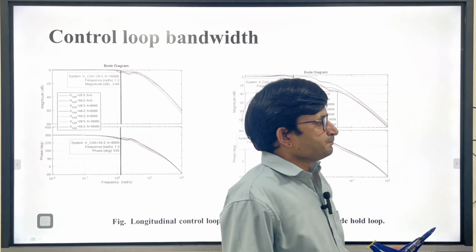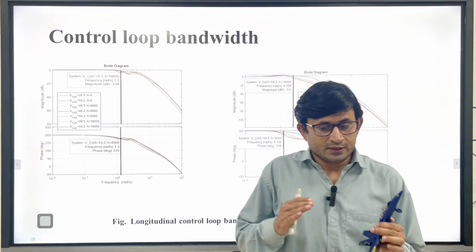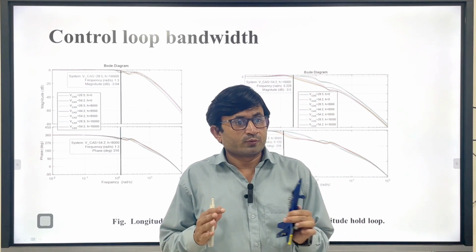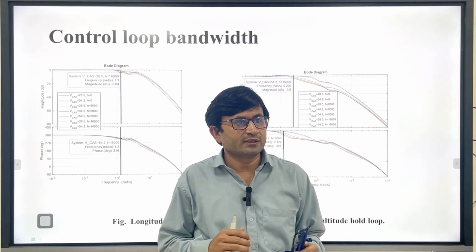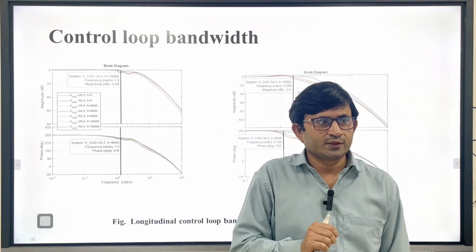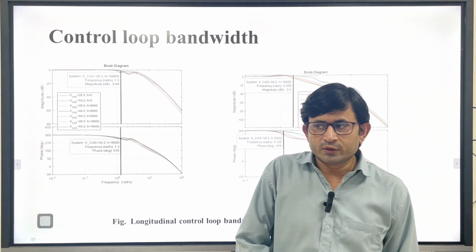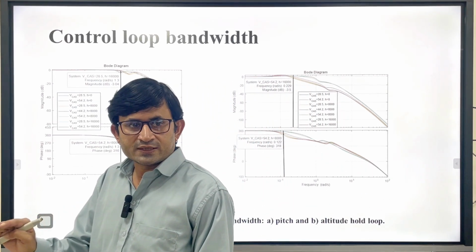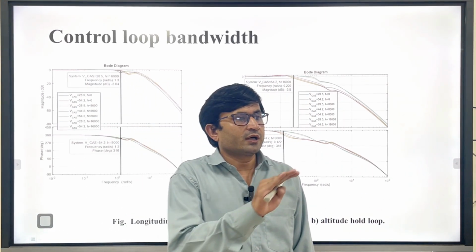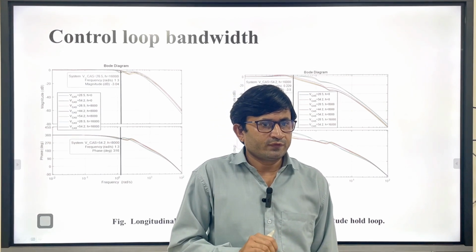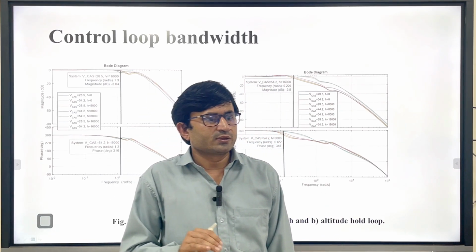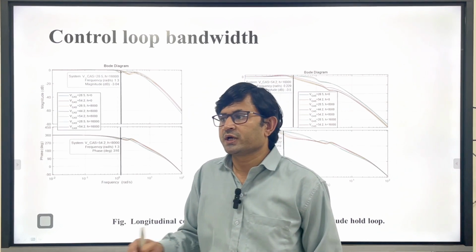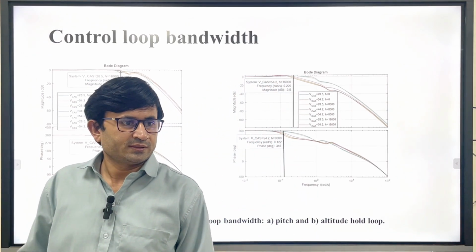Okay, and this bandwidth and robustness are closely related. For example, when you have a slow gain, your system is more robust. When you have a fast gain, your system will not be as robust. Why? Without any formula and theory, you can say when my gain is slow, then I have more time to react. As simple as that, right?